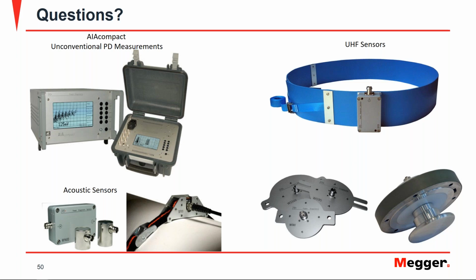Can the acoustic measurements be calibrated? Nope. The acoustic measurement as well as the UHF measurement are the non-conventional PD measurement methods, and for those, the amplitude that our measurement system picks up does not only depend on the value of the discharge itself, but also how long the signal has traveled through which geometry and signal path, and therefore no, it cannot be calibrated in picocoulomb.